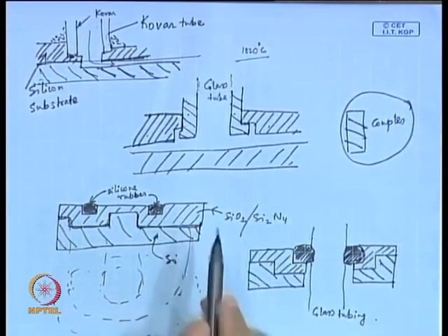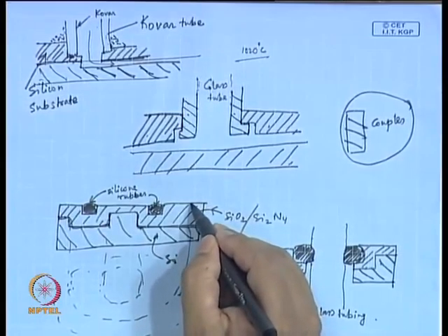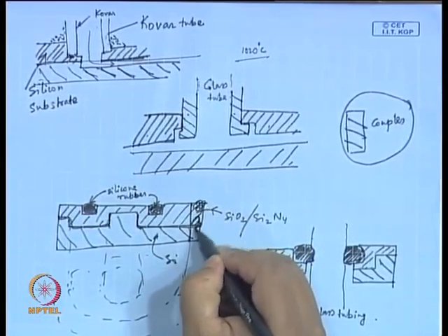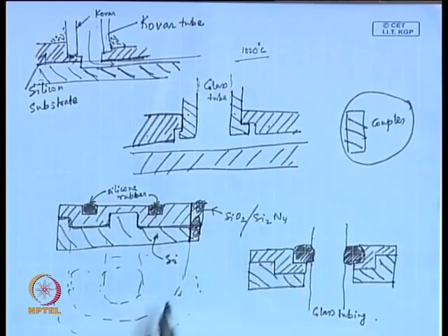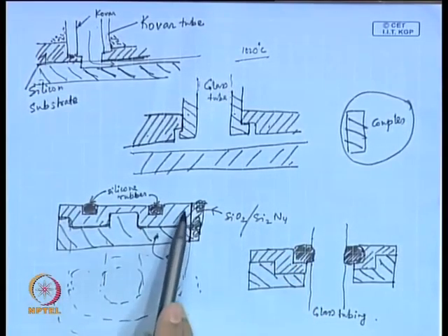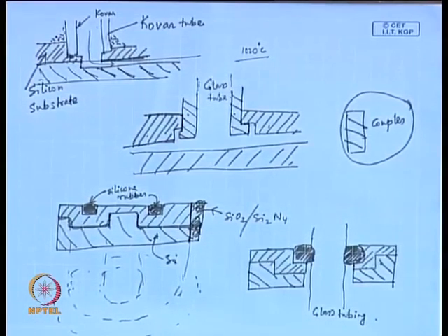Okay. So, this dip, I mind it, it should have been closed here, then it would have been uniform. Okay. So, this portion refers to an annular area. This you ensure by doing an etching, you form an annular area, then on that annular area you deposit an oxide or nitride layer, SiO2 or Si3N4 you deposit.